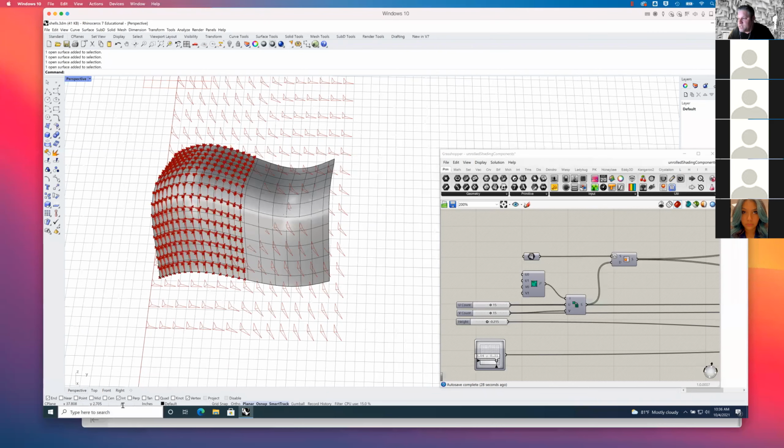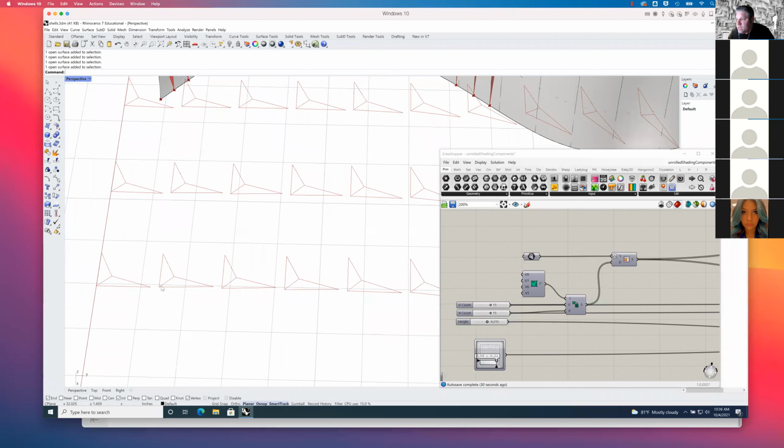So you can begin to see, in this case, I'd go through and score this edge for each one with the laser cutter, so it only cuts part of the way through the material, right? We can do that with power and speed settings in the laser cutter and just score. That way we have a nice perfect fold, right? And then I'll go back through and do a through cut to cut all these custom shapes out, right? At the same time, you'll score in a label here so that we can understand which one is which. Otherwise,